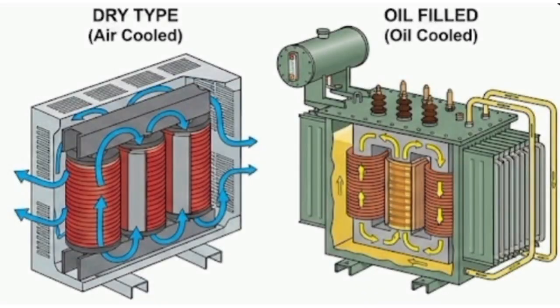When comparing oil-filled and dry-type transformers, several factors must be considered. Oil-filled transformers generally provide better cooling performance, higher efficiency, lower initial cost, and greater power handling capability.